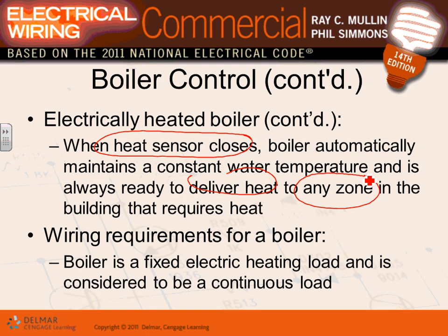The pump associated with Chad Curtis' place will pump enough hot water to the radiators in that room. Now you have a thermostat that you can set. That thermostat will control the pump. It keeps pumping hot water until the temperature in your room reaches 95. I'm just being ridiculous here with 95. When it reaches 95, guys, it turns it off. So they have radiators, or you can have an air handling unit system where you can blow air into it and whatnot. I think in this way they're using radiators.